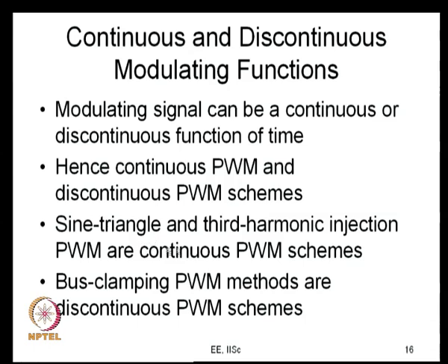Whereas it is certainly advantageous when you talk of 3 phase, and in the 3 phase it is a third harmonic injection, which gives you a higher AC side voltage now. So, the sine and the third harmonic injection are continuous PWM schemes. Sine is a continuous function of time, and in the third harmonic injection what you are adding is another sine waveform just at 3 times the fundamental frequency. So, that is also a continuous function. So, the common mode function is a continuous function of time, and therefore, the resulting modulating signal is a continuous function of time in all the continuous PWM schemes.